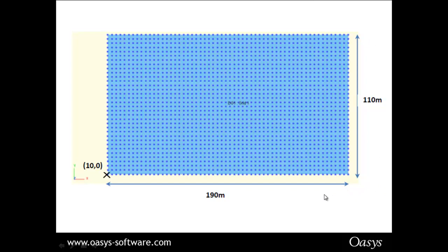So there are two ways that you could plot this. You could basically draw a line along the y-axis and extrude it out towards the x-axis. Or I could draw a line along the x-axis and extrude it out along the y-axis. And that's exactly what I'm going to do. So I'm going to draw this line here along the x-axis and extrude it out along the y-axis. And this is called the global y direction.